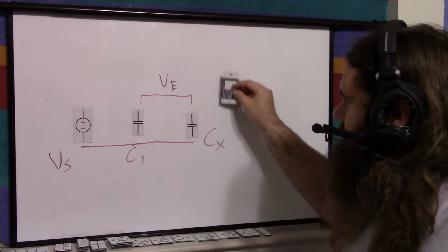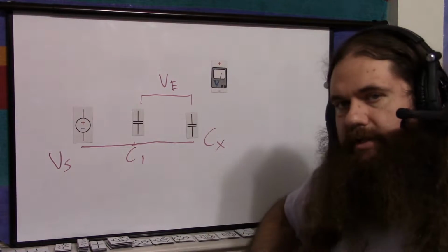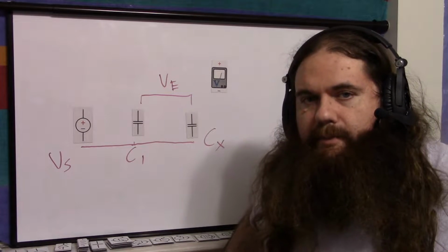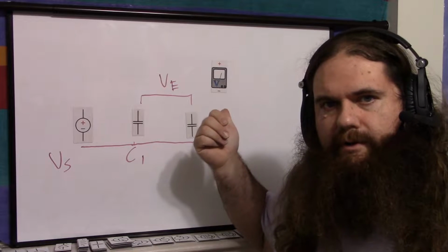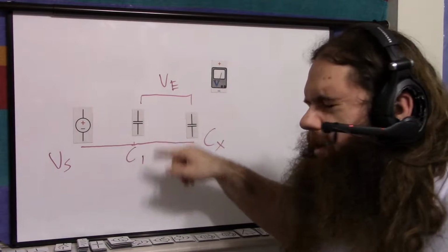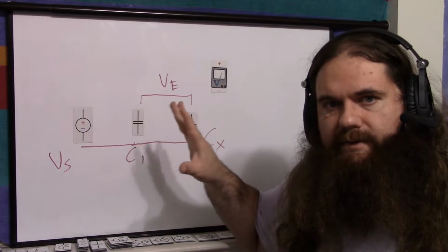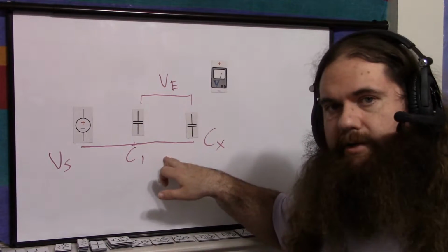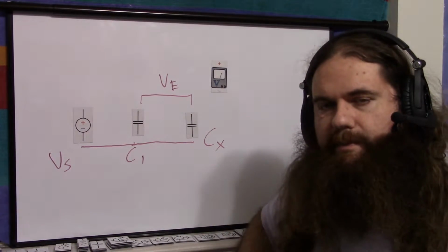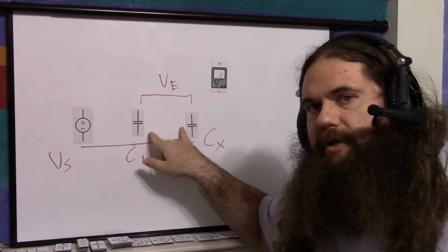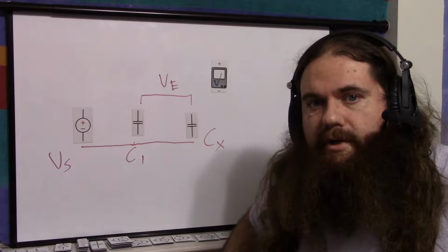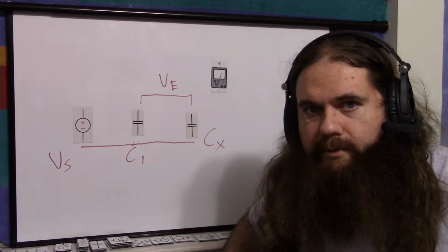Well, you can't just stick a voltmeter on there, as much as I'd like to, because even if it has a very high input impedance, it's still going to be only in the mega ohms range, which is a lot when you're talking about measuring a circuit that's live and trying not to disturb it. But a mega ohm is still going to put through a fair bit of current, which is going to drain the capacitor you're measuring. Especially if the capacitors are small, you're trying to measure picofarads, the multimeter is going to drain them fast. They're going to lose volts per second.